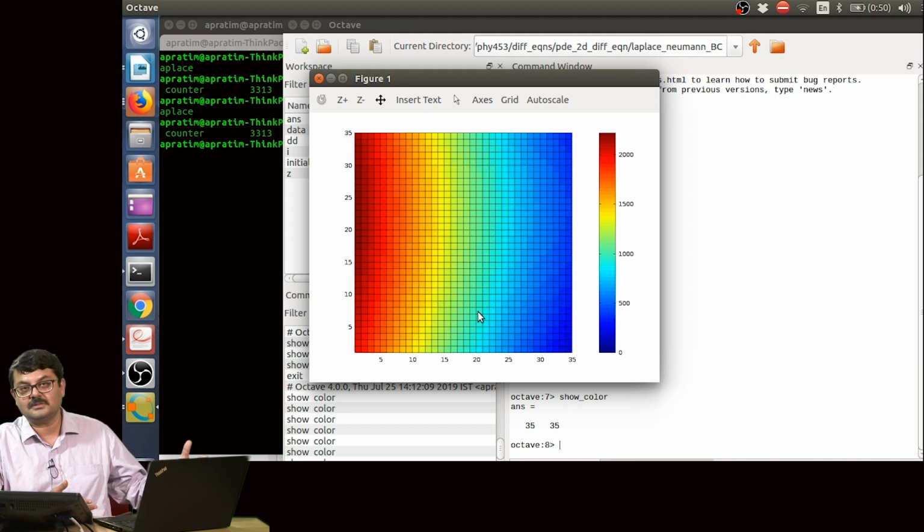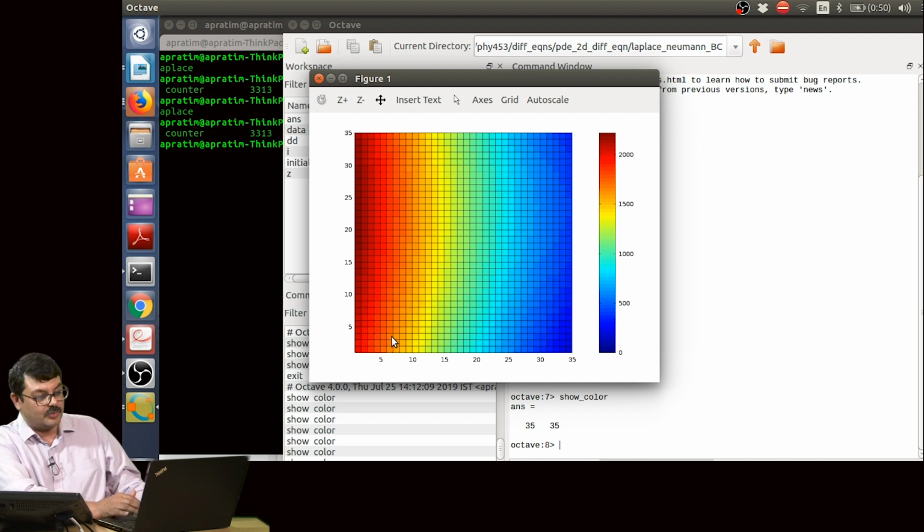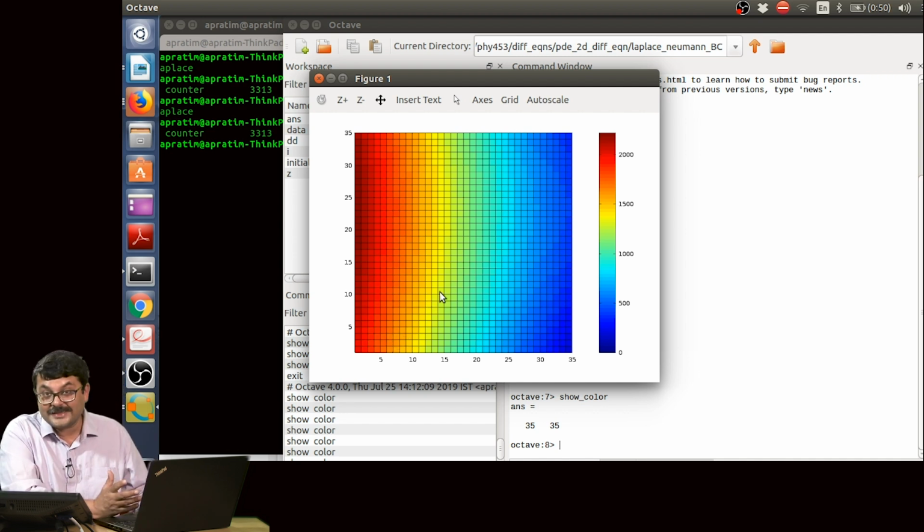Now, of course, you can put in boundary conditions so that the amount of heat current is also changing along here. So, right now it is 100 here and 200 here, and incoming heat is 700 and outgoing heat is 400. You can make them more complicated depending upon your real engineering problems or whatever problems. When you are doing a thermal conductivity problem, you can have different boundary conditions, those have to be put in, and you can find out the temperature profile, right.